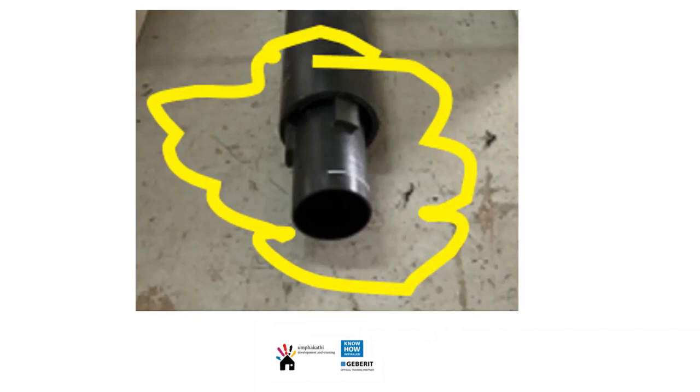The welding of this then obviously becomes problematic, as the butt welding doesn't work that well because you can't butt weld both pipes. And when we've tried to weld the 2 pipes together, we found we have a lot of failures with the workmanship of the guys welding on site.